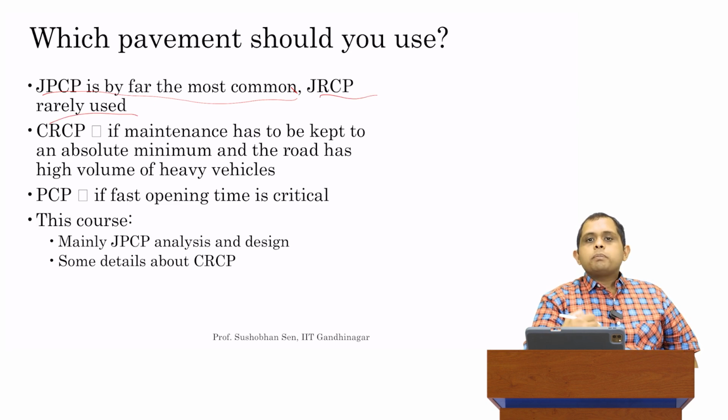JRCP is rarely used. The performance hasn't been as good in practice, and you still have the issue of joints which you have to saw. So you don't get very good performance. You still have a lot of constructability issues. So they are generally not used in practice.